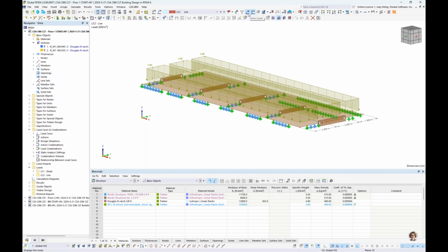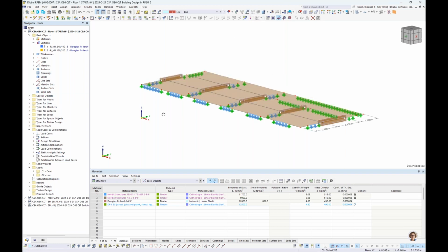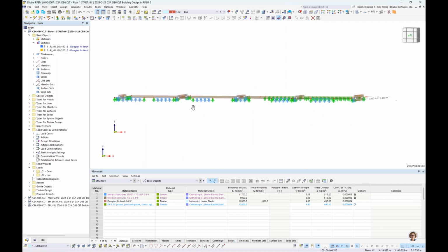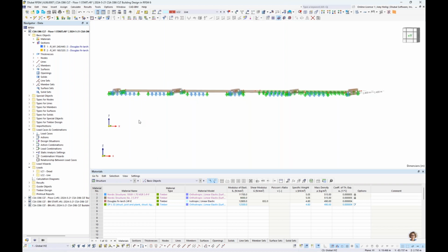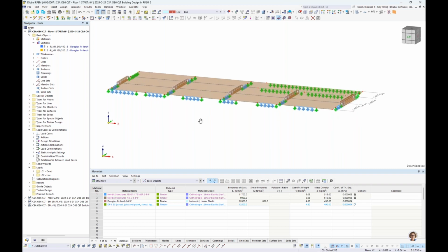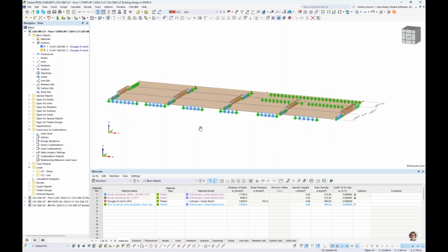Now, for these 2 load cases and for this model in general, remember we're at an elevation here of 2.75 meters in the vertical direction. And we're going to assume that this is part of a multi-level story structure. So we likely have additional stories above it, and we need to take into consideration all of the loads that are being transferred down through these additional floors to the current floor that I'm designing, because the loads that I have applied now certainly do not do that.